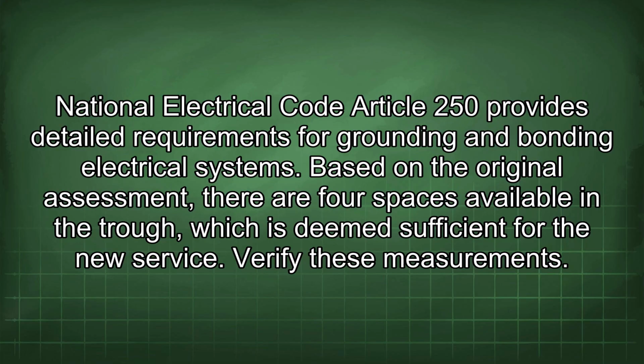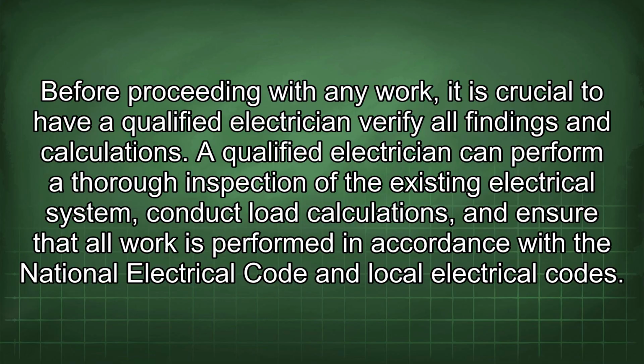Based on the original assessment, there are 4 spaces available in the trough, which is deemed sufficient for the new service. Verify these measurements. Before proceeding with any work, it is crucial to have a qualified electrician verify all findings and calculations.